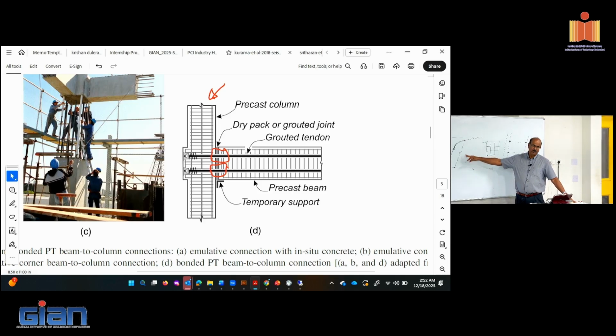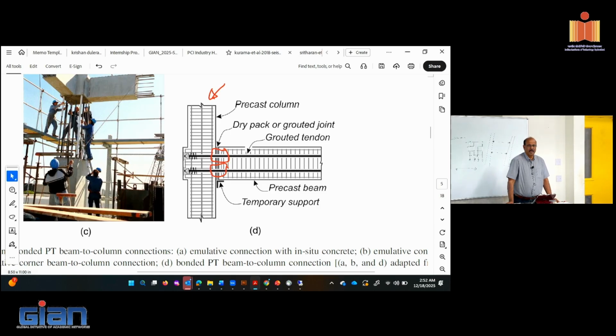Now, from this step, when other researchers in the US and other countries looked at it, they thought, why are we keeping the bonding and creating this problem? So we should go unbonded. And so that concept started to look at completely debonding the strand for the entire length. The only argument, as I said yesterday, is safety in case it breaks. But the technology is pretty good. Or you could, as I mentioned, partially bond the strands, if you prefer. So even if it breaks, you may have multiple strands. There is a highly unlikely chance that all of them break.